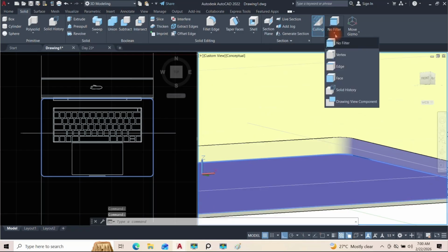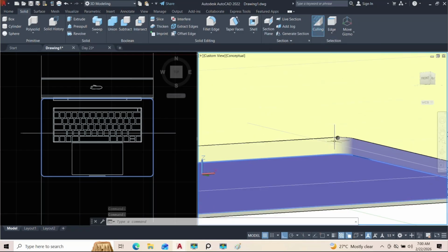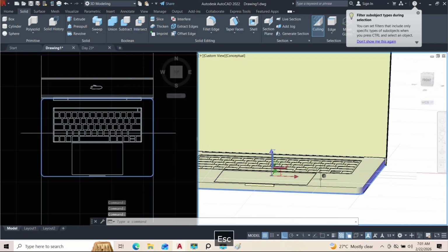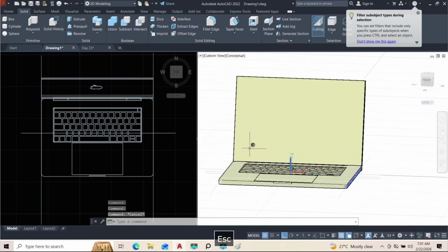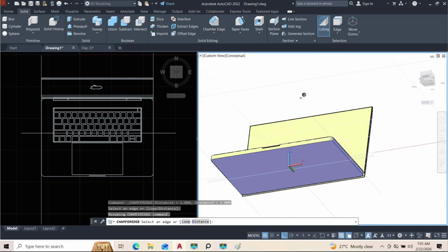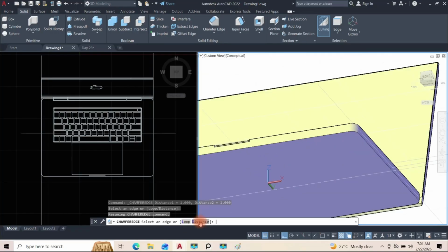okay, so let's see if I select an edge. So this will not work. It has to be a mesh for that to happen. So I think I'll just want to stop here because I don't want to rack my brain too much on this. Let's see if I use chamfer, maybe that will work. So chamfer distance, we just try to look for a particular distance.